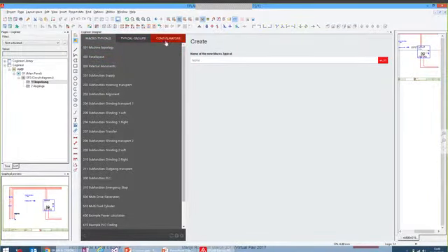And there we can see we have 2 pages in our library, or even 3, with just the supply, the first supply, the second one, and also the 3 fuses. So this is linked. So let's have a look into our macro typical here, which is directly linked to this macro, of course. And we will see here that, in fact, like we showed you, we have 3 selection lists of feeder 1, feeder 2 and feeder 3. And remember, we could choose 2, 4 and 10 amps.